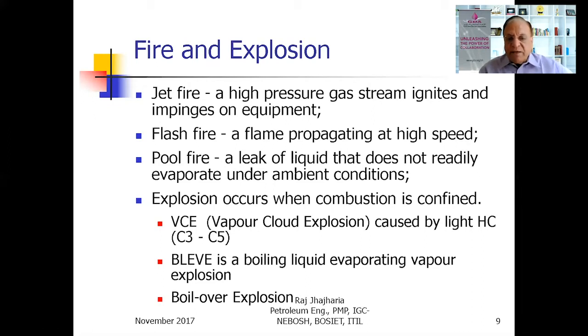But let us say there is a fire in the neighborhood, just like the jet fire or another tank is burning or something is happening in the neighborhood. And because of the heat, that heat will start making the tank also hot. And as this tank starts getting heated, the water which is deposited at the bottom of the tank will start getting converted into steam.